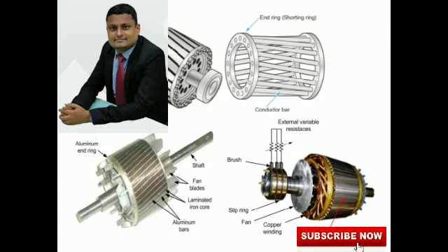Now rotor core. Flux density in the rotor core is generally equal to or at most 10% more than the stator core flux density. So write down BCR equals 1.0 to 1.1 into BCS. Depth of the rotor core DCR equals phi by 2 BCR into Li. Inner diameter of the rotor, shaft diameter, Di equals DR minus 2 into (DSR plus DCR).